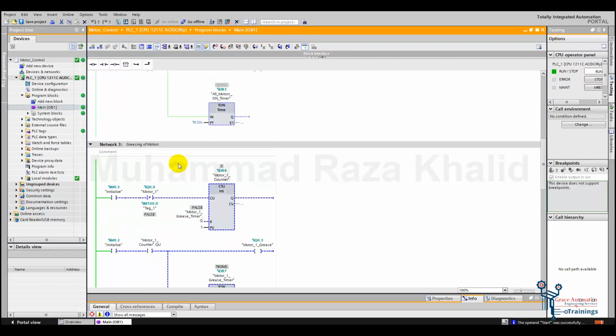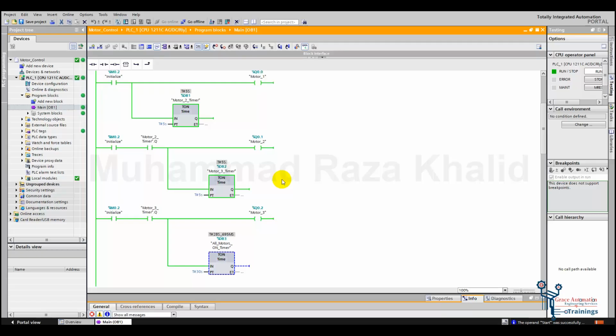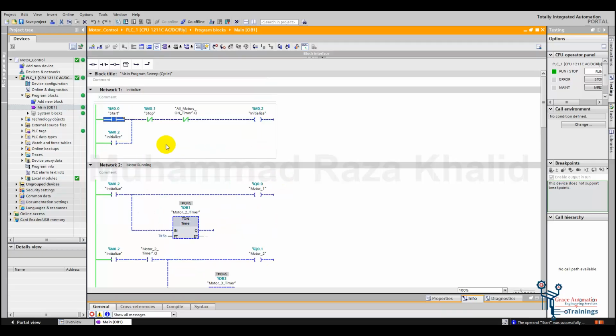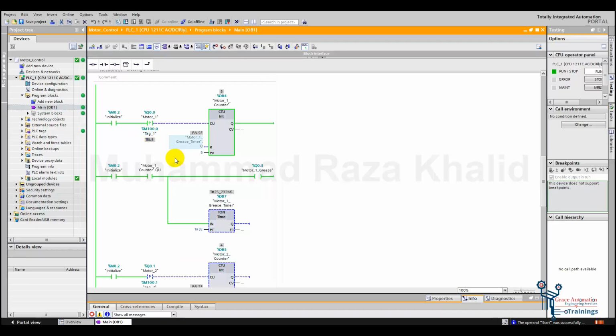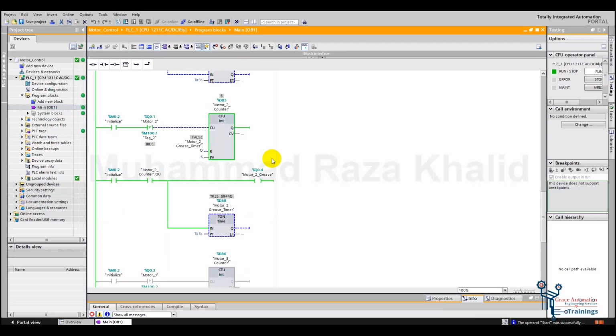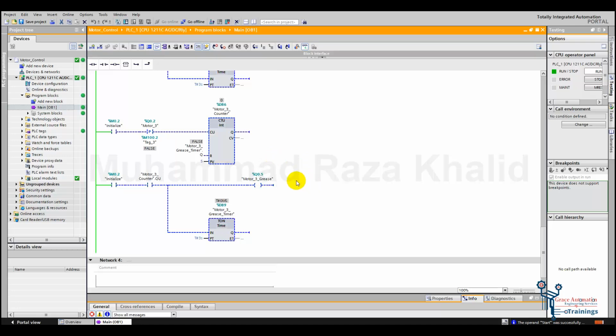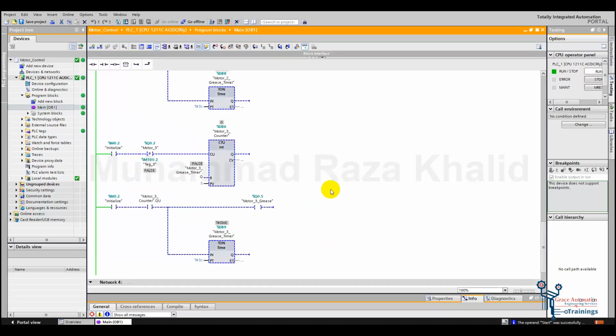So let's turn on the motors again. Now these have turned on 4 times. Now finally, let's turn on the motors for the 5th time. Here we can see that lubrication turned on for 3 seconds and then it turned off. So the logic is working fine as per the requirement.